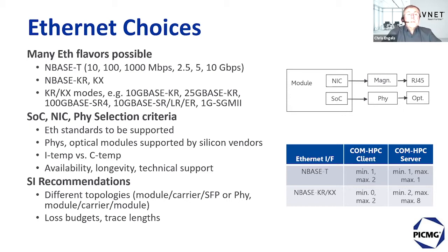And there is a relationship between the network or system on chip devices located on the module and, for example, the PHYs which are supported in that combination. So this is a very critical selection step. It's very, very strongly recommended that you work with the supplier of the module to identify the right components which belong onto the carrier card.